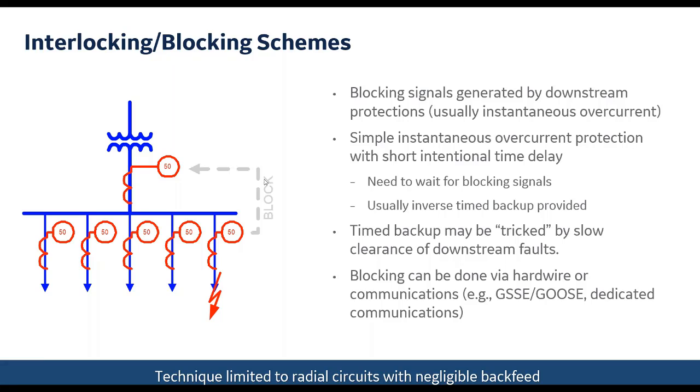You could have a maloperation because you have these grounds. You might have a relay failing to operate because you're not getting the signal to where it needs to get to. And when you go to test it, the water has dried up now. It's gone because when you're testing it, you're not testing it in the middle of a snowstorm or when the snow is melting. You're testing it on a clear day. So the issue is gone. So it's impossible to troubleshoot and find where the issue is.